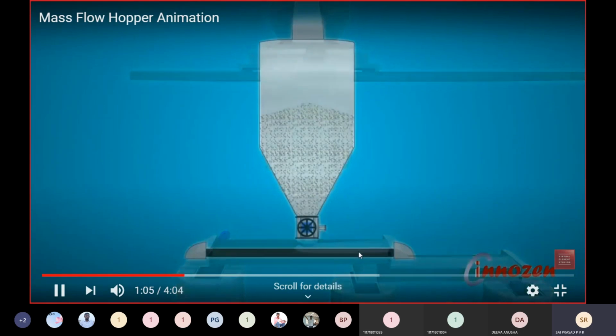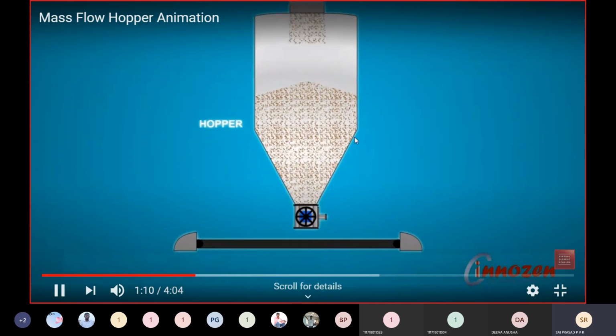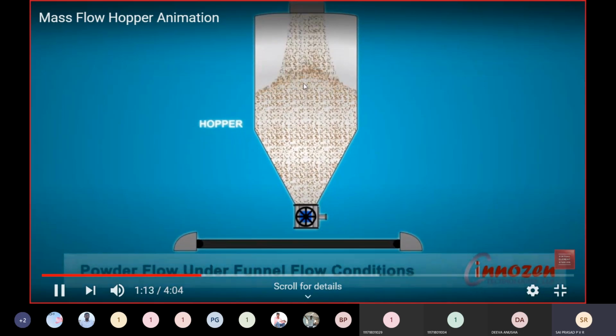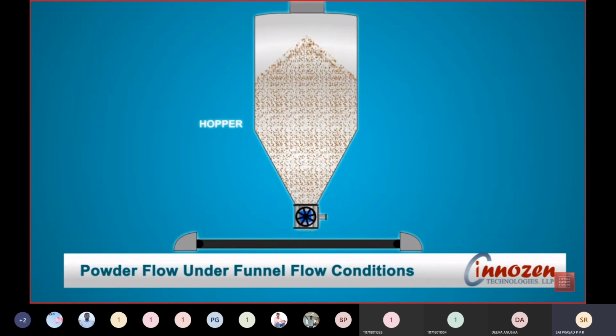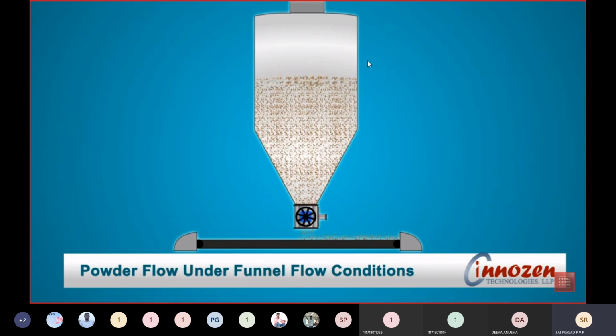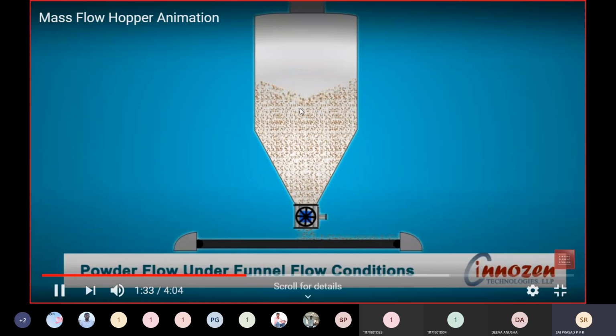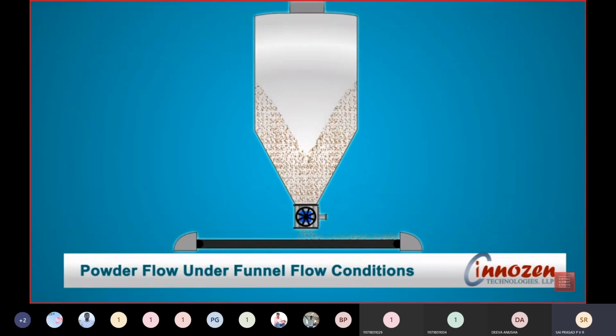From there, it is discharged out onto a belt conveyor. This is the feeder. This is the part of the hopper. And the materials are dumped. See how the pile extends. When we have a feeder, we don't have any problem. That feeder will be continuously dosing to the conveyor belt, and the material falls into the system. This is called a feeder to the next process. To ensure m dot constant, we do this.